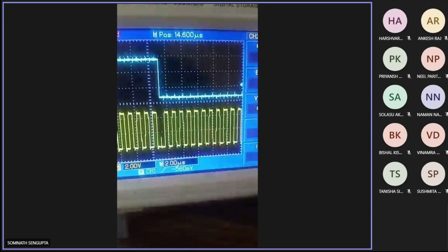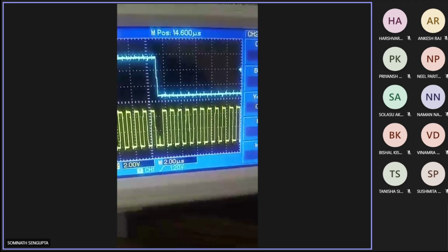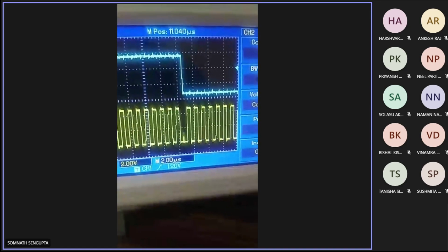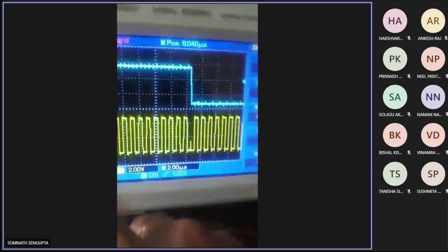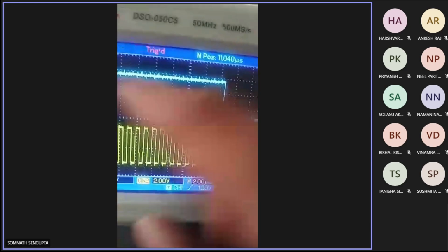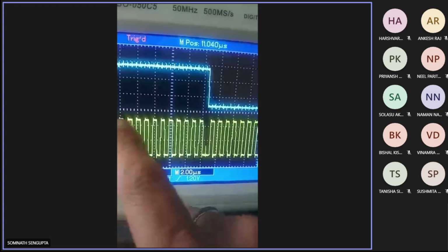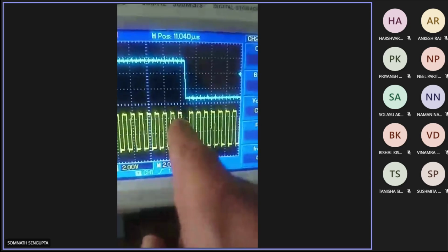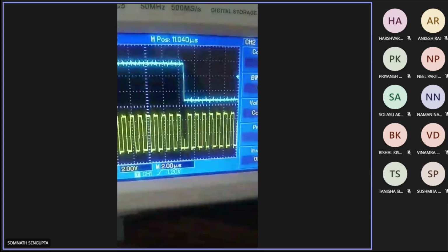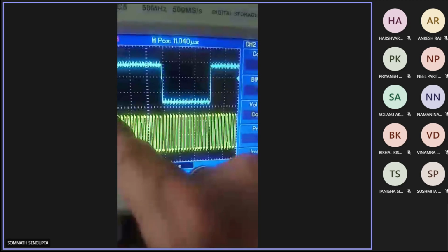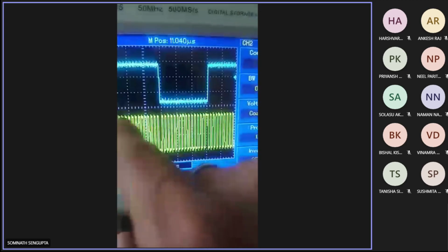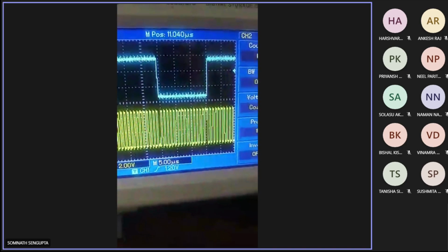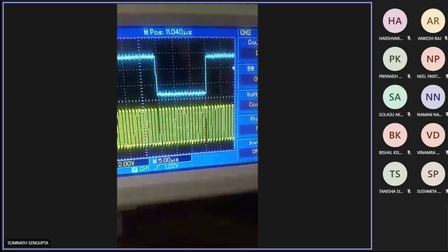And you see another important thing, how many transitions should be there. If we count it, it is actually 1, 2, 3, 4, 5, 6, 7, 8, 9, 10, 11, 12, 13, 14, 15, 16. 16 for logic 1 and another 16 for logic 0. Logic 1 16, logic 0 16. So total near about 32 or 33 transitions.